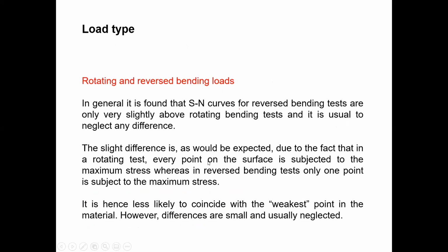In this slide, they explain that the weakest point is the loading point. When you apply the load, that loading point is the weakest point, because it is the higher bending moment point, where the maximum stress is available. So still we don't have any stress concentration point. In the specimen, assume this is supported at the two ends. If you apply load like this, this is the point where maximum stress is available, so this is the weakest point.